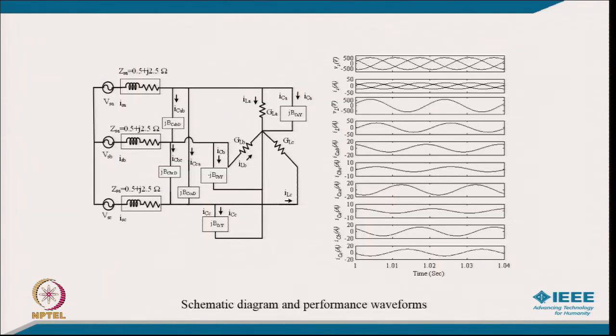So, we have typically a star connected load, and a 6-element compensator after the source impedance. So, we will be having power factor correction, load balancing, and then after that we will have voltage regulation. After getting all those relations, after design, we have plotted the waveform with those compensator values, and we come to a balanced load at unity power factor, as well as voltage regulation also.